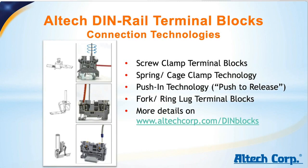After discussing the types of terminal blocks, we now come to the three main connection technologies for thin film terminal blocks: the screw, spring, and push-in technology. From a historical point of view, the original terminal blocks were invented with screw clamps, so that was the original connection technology. Later along came the spring clamp technology, and the newest technology on the market is the push-in technology. Some also know it as push to release.